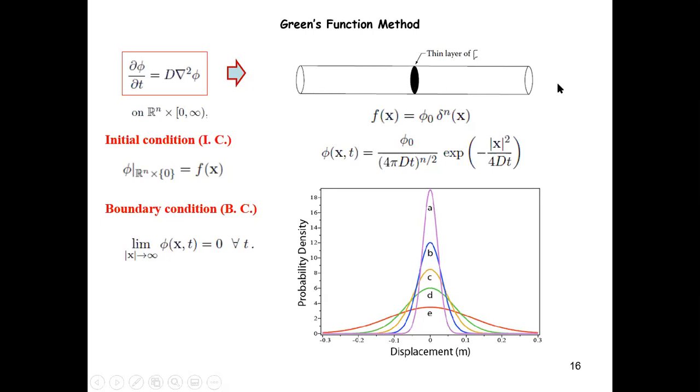But typically, we wouldn't be able to wait that long for real engineering applications. We wait for a sufficiently long time and increase the temperature a lot, so the carbon penetration is very fast. Eventually, we won't get a perfectly uniform distribution, but a more or less uniform distribution based on these processes. So that's basically it for this particular one.